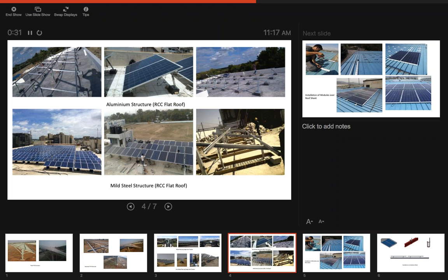So you're saying that this is an in situ casting in ballast. In an in situ casting, we are using nuts and bolts coming out of the foundation. Yes, anchor bolts, which you can see in this part. In any of the foundations, the base plate comes at the bottom of the structure. That base plate is fastened to this foundation using anchor bolts.